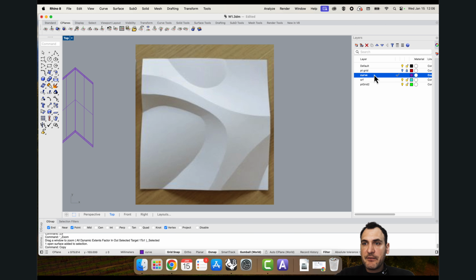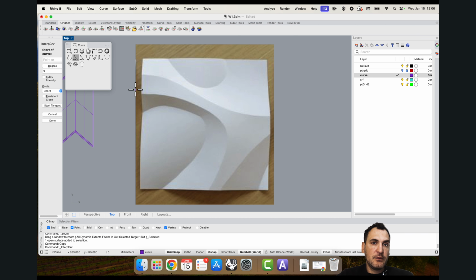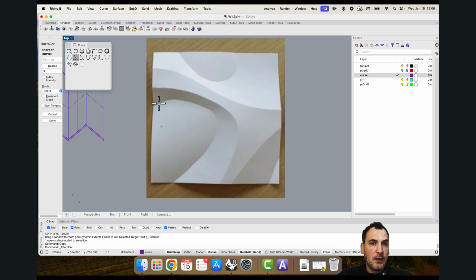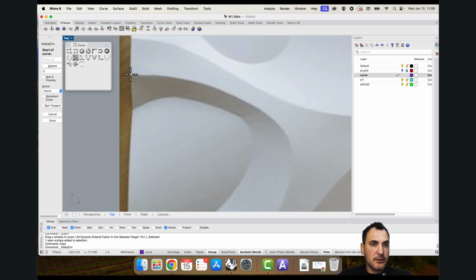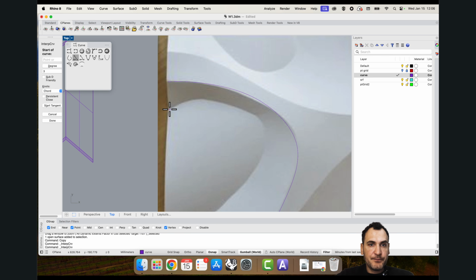So what I do is I first go to the Curve tool and then open up this tab here, and since we are tracing an image, we want to interpolate points, right? We want to grab certain points on the curve, on the image itself. And for this, you don't want the grid snap to be on, so you can turn this off, and you can come down here and then start placing some of these points and see if you can extract the curve.